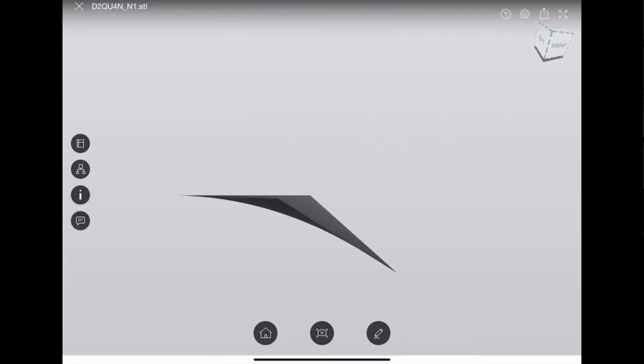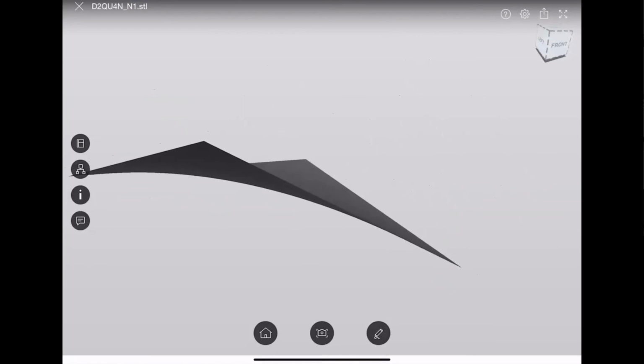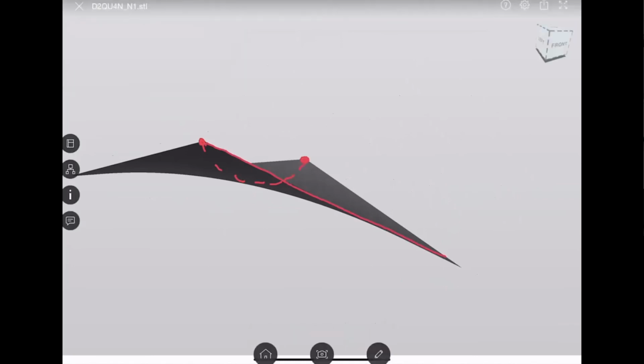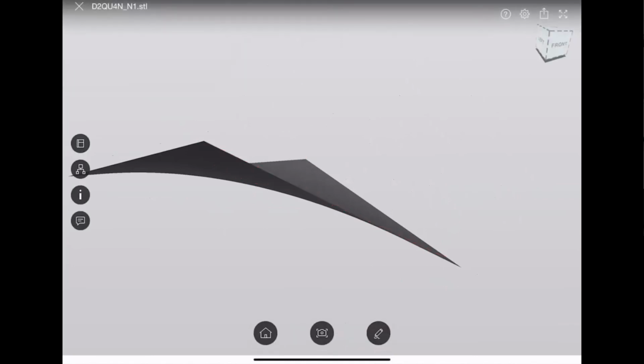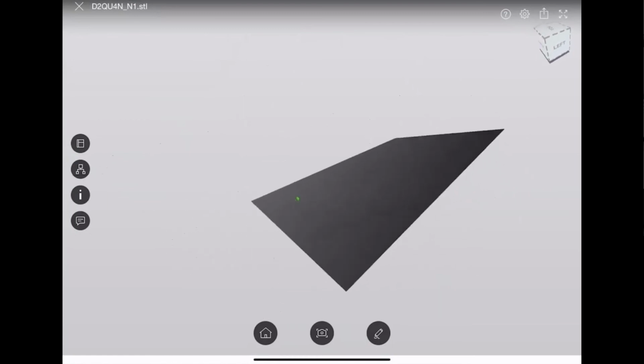Do you see what I'm trying to say? That from this corner node to this corner node, it is not a line. It's actually a quadratic function, but these are straight lines. So on the edges, you get straight lines for that element, but at the center, you get that shape, which makes sense.